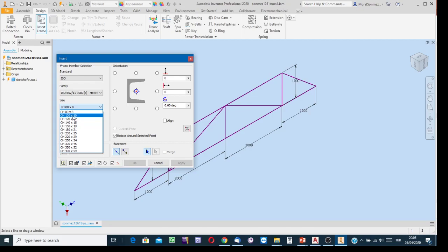Well, say that the height of the cross section, say 100. I selected this one, not arbitrarily, of course. I solved the design problem, and I know that to be able to make the members strong enough under the action of the forces acting at both of the terminals, if the size of the cross section becomes equal to that much, then it is going to be sufficiently strong. Okay, and also in this size, it is going to be stable. Cylindricity check also saying that, yeah, this is the correct size. While you're taking design course, strength of materials course, you're going to learn the necessary things and understand what I mean. Say that this size is determined by the designer.